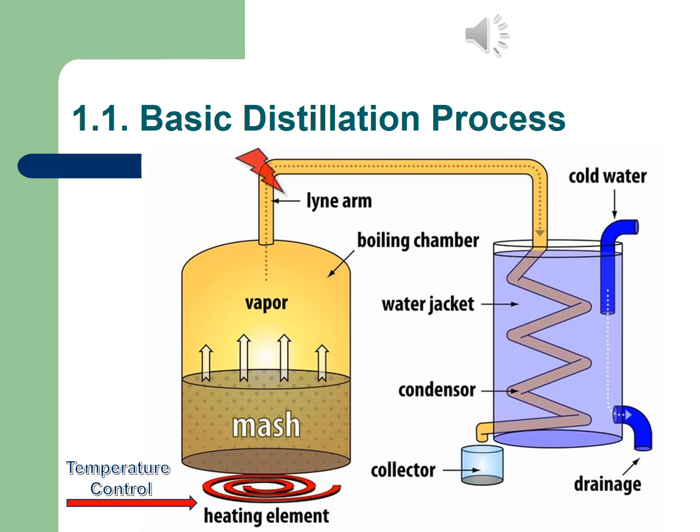Okay. Then also what you can do is, after you extracted everything and basically the vapor stopped, you can actually move to a higher temperature, 78 degrees Celsius, and you can then collect your ethanol. Now that ethanol eventually will also stop, because it means that everything will have turned into vapor. It will be cooled down. So looking at the different components, you have your mash that's inside the boiling pot. You need to control then the temperature very closely. That vapor will actually move into a cooling section.